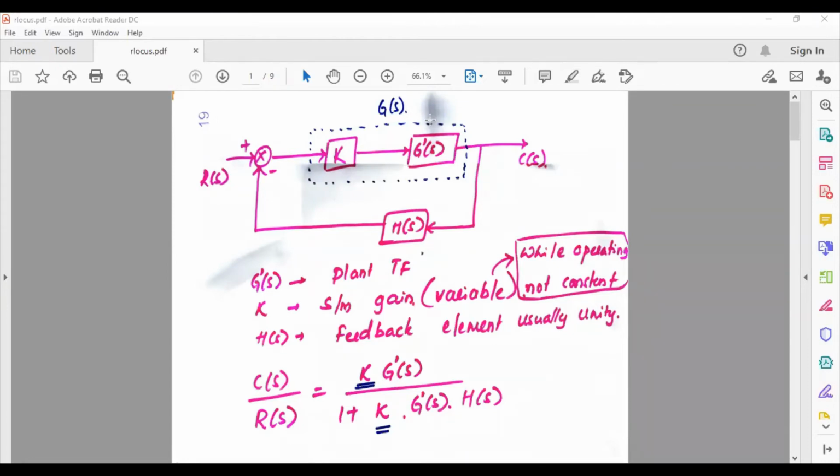But where does k come in the transfer function? The existence of k in the transfer function just gives you an idea that the transfer function has different dynamics for different k. See, 1 divided by ms square plus bs plus k is not the same as 10 divided by ms square plus bs plus k, right? Now k has changed to 10. So similarly, it will have a different transfer function when k is changing. So k is as good as a system parameter and is related to system dynamics only.